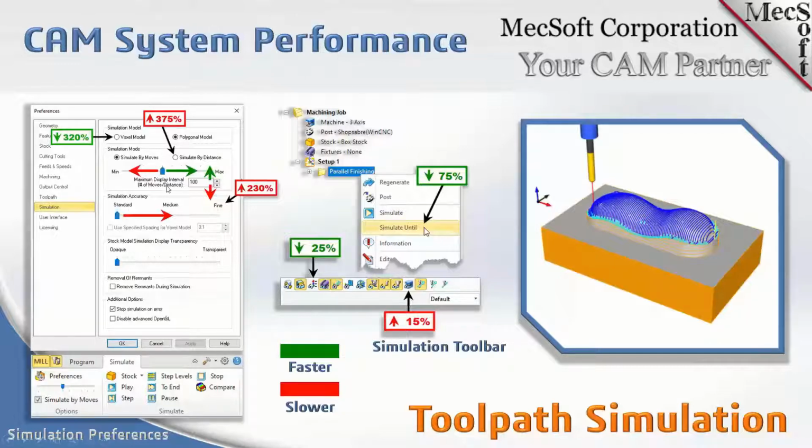You can control that by simulating by moves and adjusting this value right here, the maximum display interval. The default display interval by moves is 100, so every 100 moves the simulation on your screen is going to refresh.